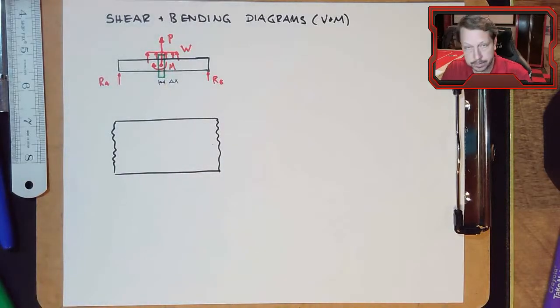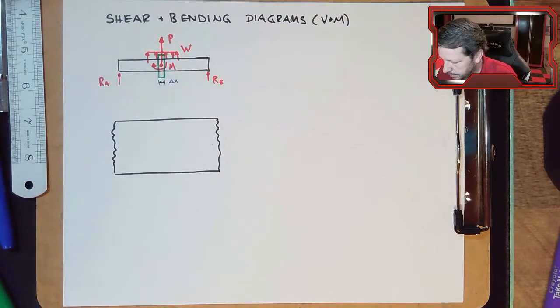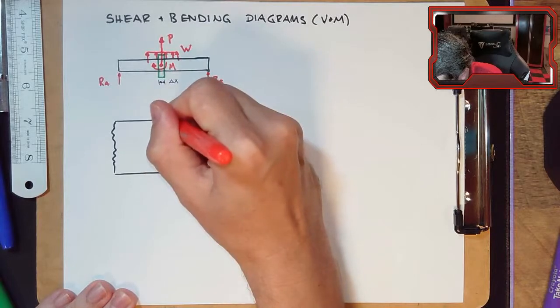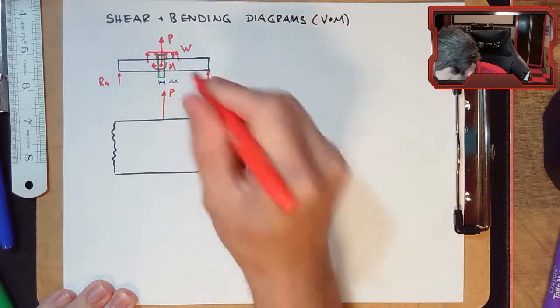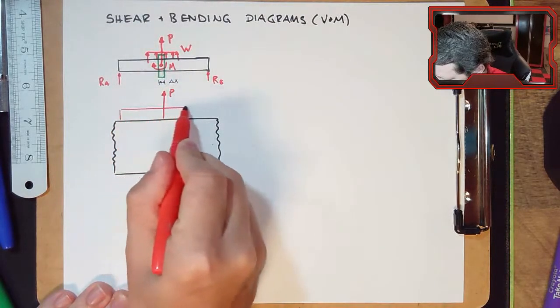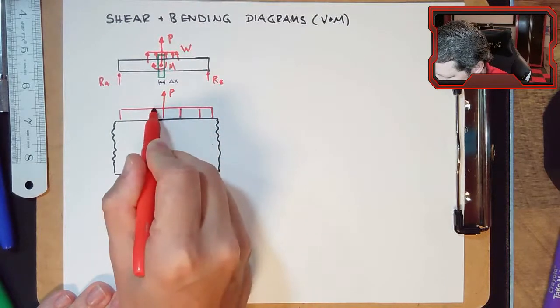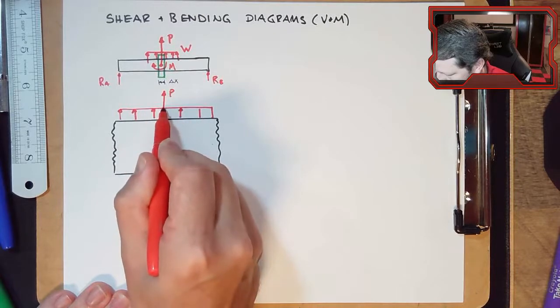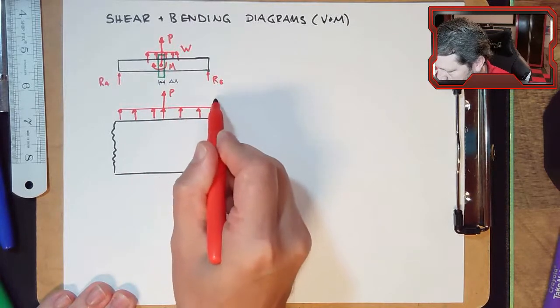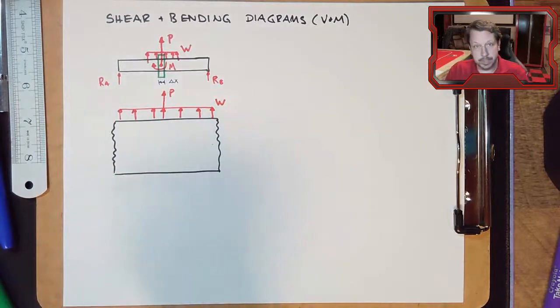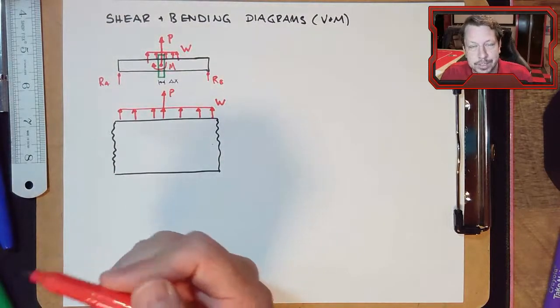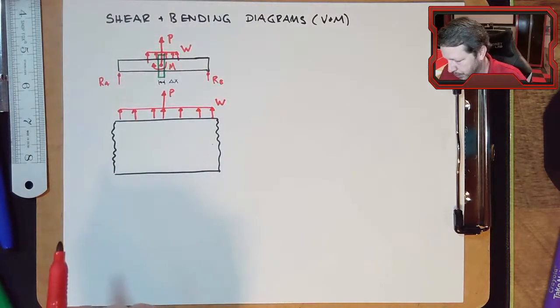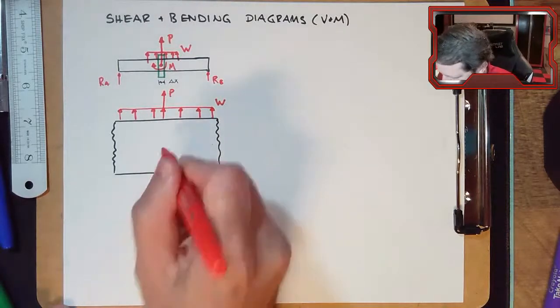And it has all of these loads. We cut out the point load, P. We cut out our distributed load. And we're making them all go in our positive direction. That doesn't affect how we will actually solve things once we develop our rules. It's just so that our equations end up with positive variables in them. We also put this moment in here.